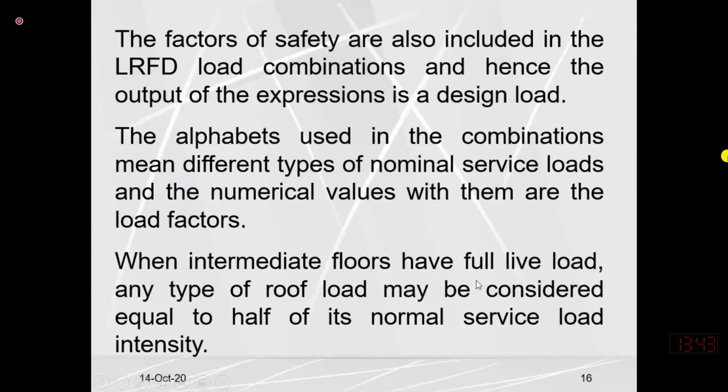When the intermediate floor has full live load, any type of roof load may be considered equal to half of its normal service load. Okay, there is an example, unrealistic. For example, we have a two-story building.